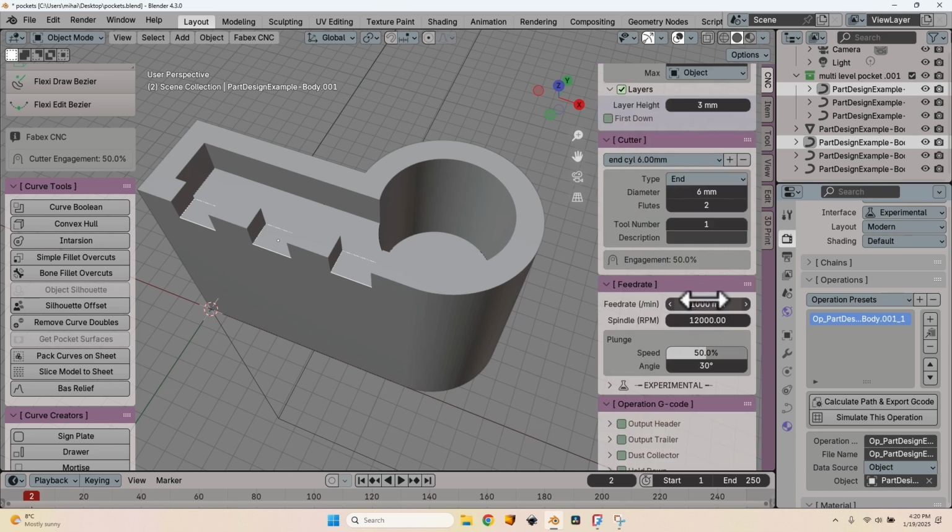So now let's set the feed rates. Here again it is something a little bit different than other software, other programs. I will use a feed rate of 3000 millimeters per minute and the spindle speed of 18,500, but this feed rate represents the speed on the two horizontal axes, the X and the Y. After setting the spindle speed of 18,500 RPM, I'm going to set the feed rate on the vertical, on the Z axis, which is a percentage of the feed rate that I have set for the X and the Y. If I want the same feed rate, I'm going to use 100%.